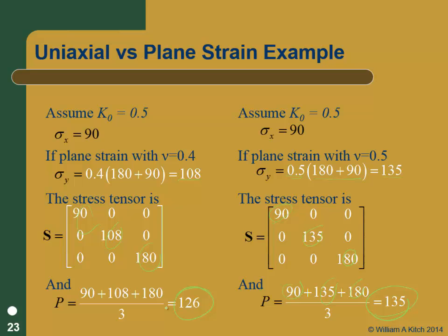When we do plane stress, we do a lot of things in 2D. The real point of this is we do a lot of things in 2D in soil mechanics. We don't really think about the third dimension. Well, the third dimension's there, and so we're making some assumption about the third dimension. We just do two-dimensional analysis. Normally, that's appropriate when we have something that's really long compared to the width. We can make it infinitely long.